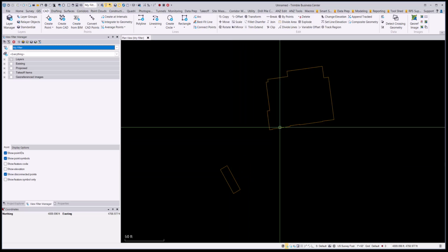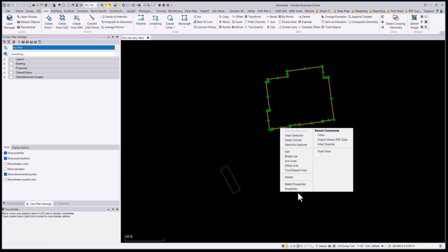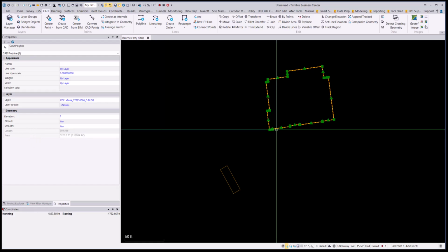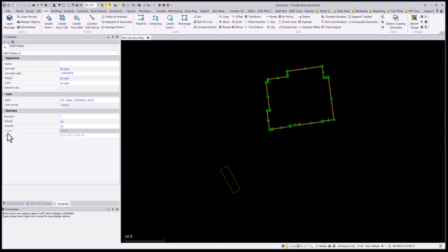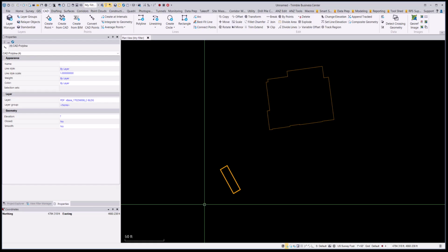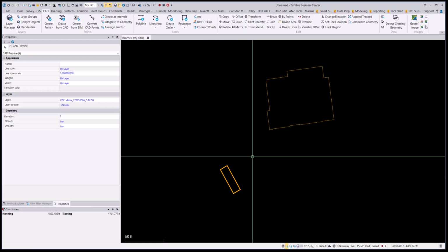And how you can tell is if you pick on that item and do a properties window, you can come over here. If you have a closed item and you do a properties, it will give you the area of it, okay? So you can actually get an area of an object if it is closed. All right, now if I did it here, these aren't closed entities, right?